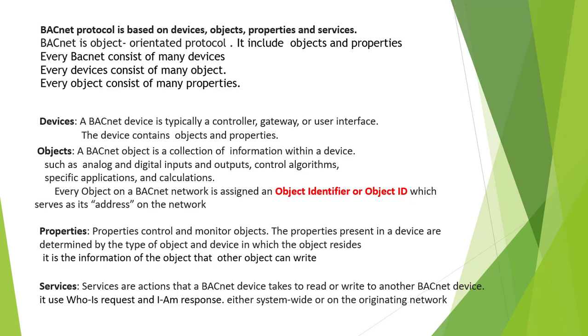BACnet protocol is based on device, object, property, and service. BACnet is an object-oriented protocol. It includes objects and properties. Every BACnet network has a lot of devices. Every device has many objects. Every object has a lot of properties.